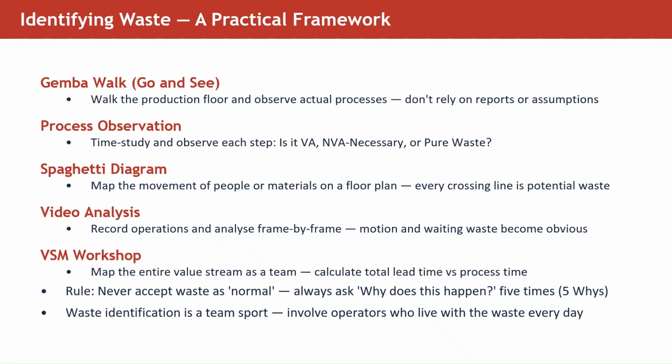Find out everything. Make a spaghetti diagram. Map the movement of people or materials on the floor plan. Every time something moves from one location to another, you draw a line. The resulting tangle of lines will reveal the transportation and motion waste visually and powerfully.